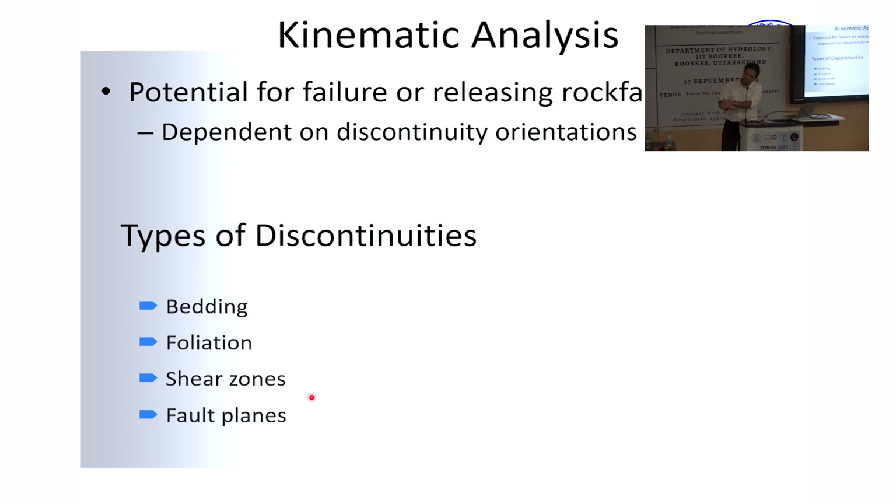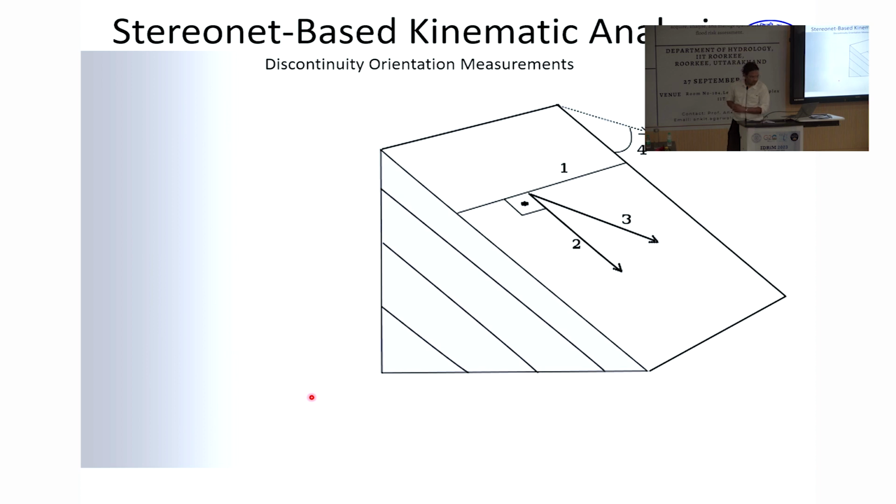The other way is to get the X, Y, and Z intercepts. If we have the intercepts on the X, Y, and Z axis, we can orient a plane. One of the easiest ways to orient the plane is if we know its slope, which in geology is called dip. This is a very important word which you should remember. So this is a horizontal plane. If we know the amount it is slanting or sloping from horizontal, and we know the direction in which it is dipping, north, east, west, south, etc., then we can orient a plane. Please remember this. This is how we orient a plane.